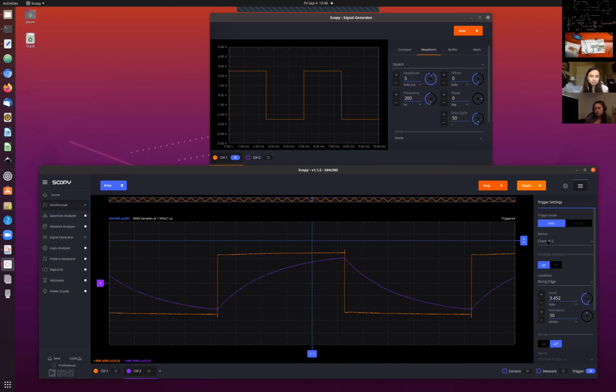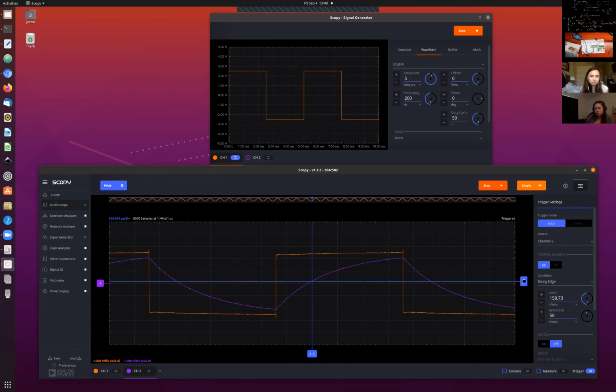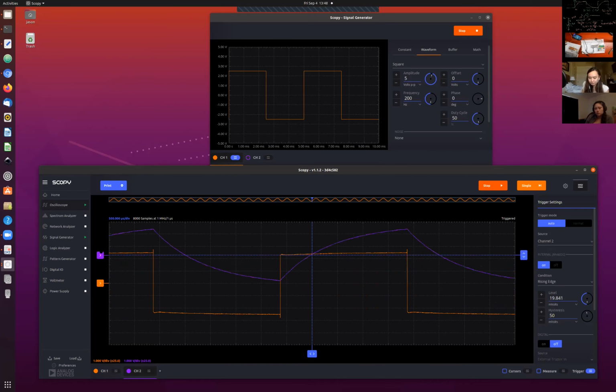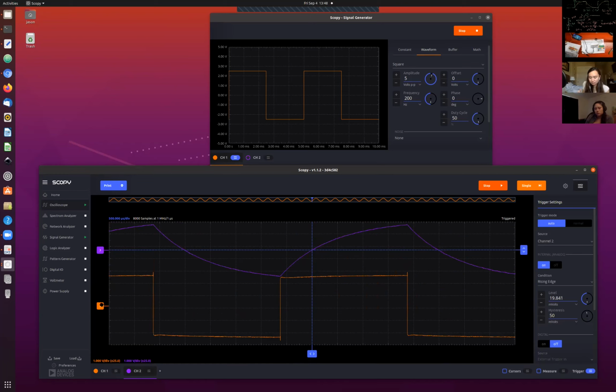So you have to look, okay, I'm on channel 2, my level is too high. Let me set the level such that channel 2 actually crosses that level. And that's separate from moving the whole waveform up and down. So I can move the whole waveform up and down just to put something on top of something else, as opposed to I can rearrange the screen like this.